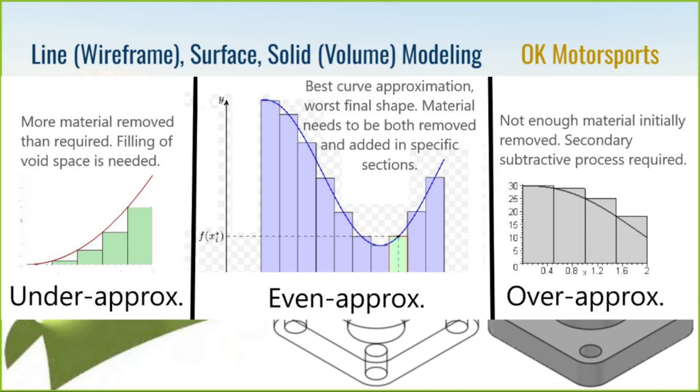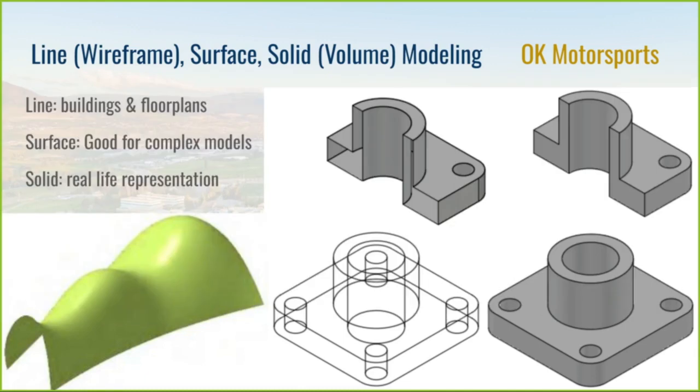More. So after we cut off all this extra material, we have these steps where there's more material here that needs to be removed. What we do afterwards is we have this rough looking thing, looks like Minecraft almost, and you can take a sander to it or a chisel, and you start buzzing it down so that eventually you get this smooth shape. You can't tell if you've taken off too much, so if you get ripples in it, it's up to your discretion to understand that, hey, if I start taking off the edge, as soon as this point disappears, I'm at the limit. I can't sand anymore. If I sand anymore, I'm actually going past the surface.